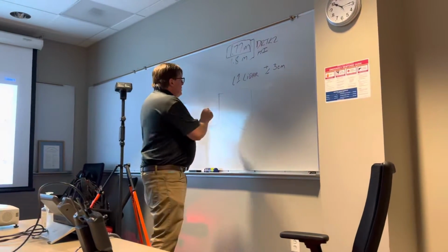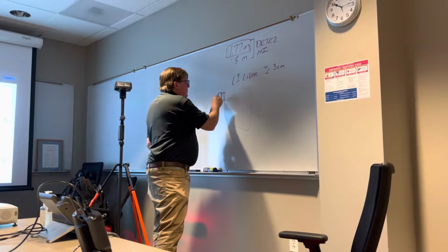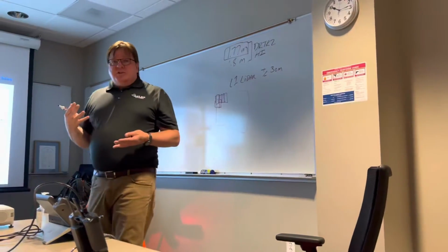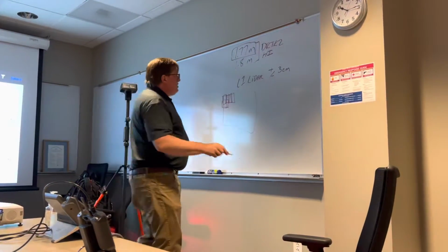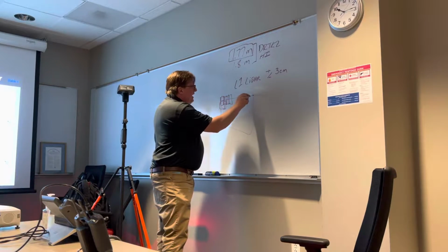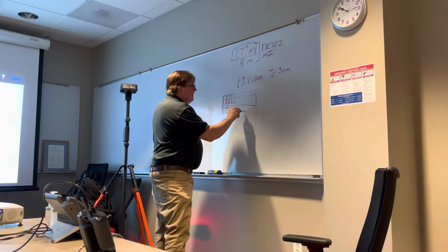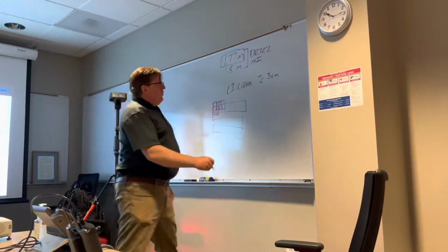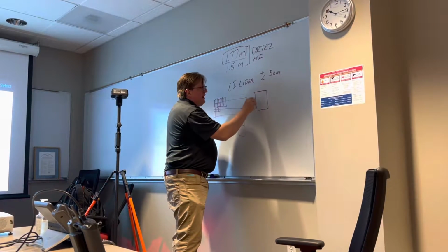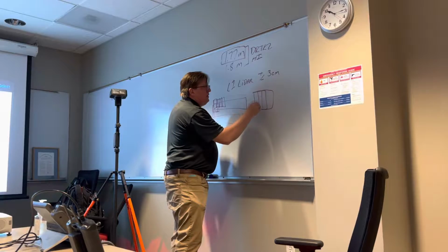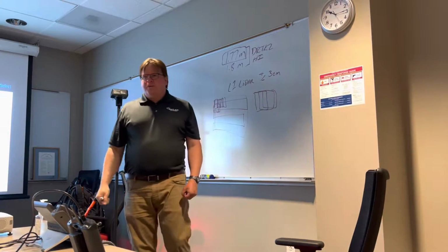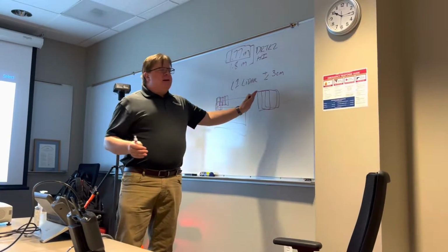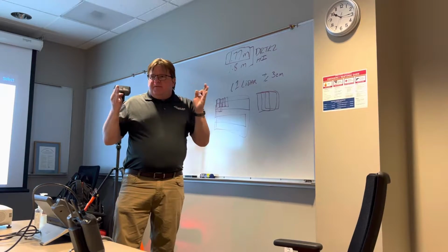The way photogrammetry works, you take a series of photos on a site, and you're building a matrix of stereoscopic images. For each line that you fly, you basically fly a site like you mow a lawn, so you cover the entire site. For your series of images, each new image only collects 20% more data, so you get a very high stereoscopic view as it's going.